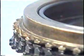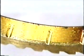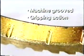The synchronizer ring has a beveled inner cone that mates with a similar cone surface on the drive gear. The synchronizer ring's cone surface is machine grooved to provide a gripping action when it's forced into contact with the drive gear. The gripping action of the synchronizer ring as it's forced onto the drive gear during a shift brings the drive gear up to the same rotational speed as the clutch hub and sleeve. When the drive gear and clutch hub are rotating at the same speeds, the sleeve can easily mate with the drive gear without clashing, providing the synchronized shifting feature.